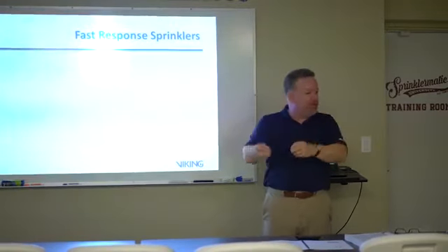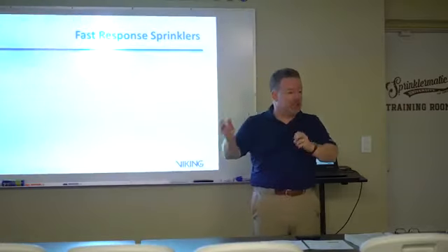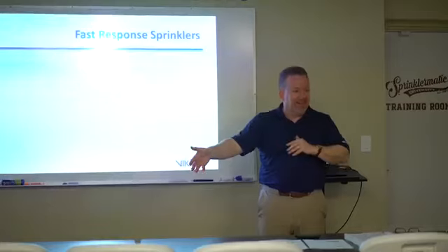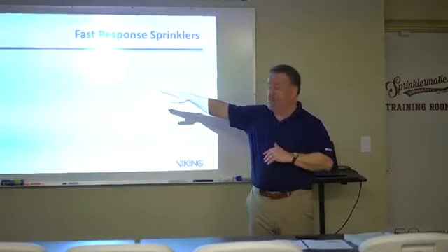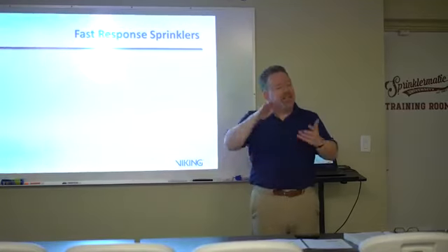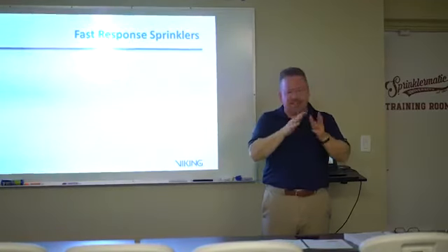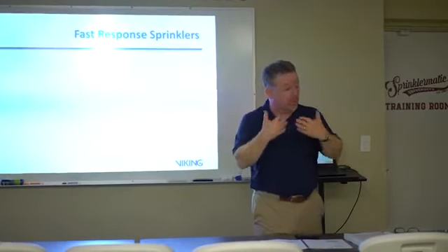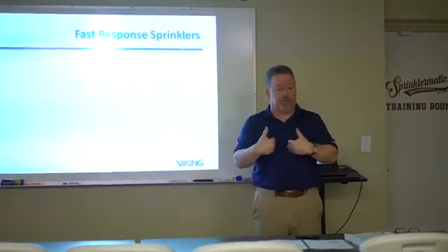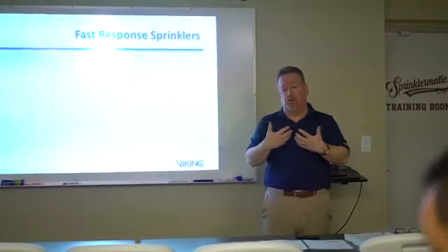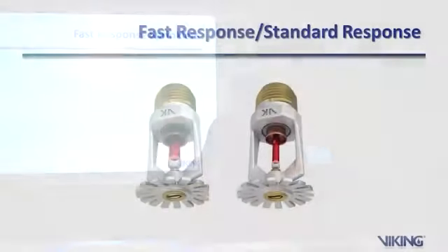The sprinkler that uses the fast response link is usually termed a quick response sprinkler, except when it comes to the ESFR, which is early suppression fast response. So it gets a little confusing. The term typically used for the sprinklers that are going in is quick response sprinklers, and a residential type of sprinkler is also a quick response sprinkler.